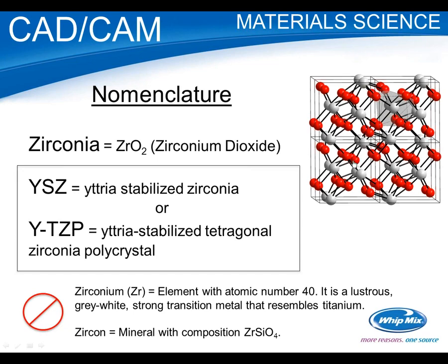So I point this out because on the zirconia, we're not going up to a melting point where it goes from solid to this kind of liquidy state, to fuse. It's going to stay like this its whole heating, sintering process time. So it really is different than porcelain. So later when we talk about how we have to treat it differently, hopefully this will help and that'll make more sense.